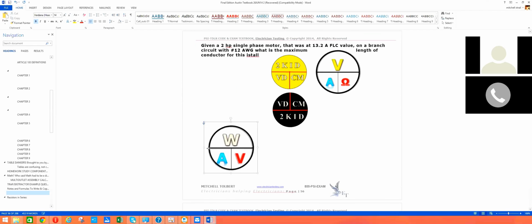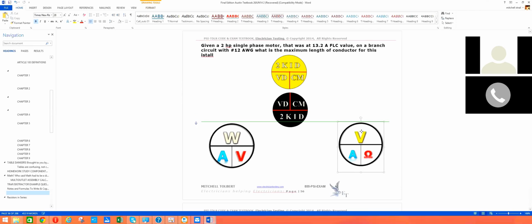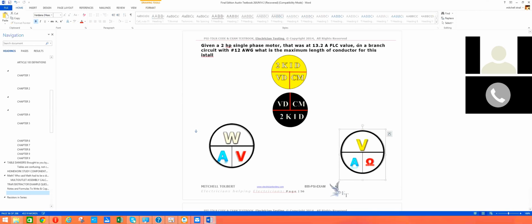basically, and I'm not going to get into detail with it here, but just to give you an example, that's going to use one of these 2 formulas up here when we're talking about voltage drop. Now, you can have a voltage drop question with a resistor or a set of resistors in series, and that's a different voltage drop. In fact, it's really a voltage loss kind of question versus a percentage voltage drop up here. Because once we have conductors in parallel, we shouldn't have any voltage drop technically or theoretically, or wouldn't want one to occur if we could help it.